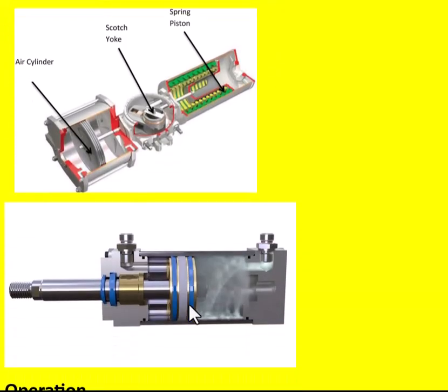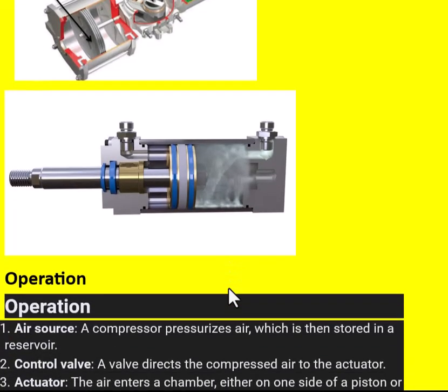And this is how the original instrument looks. This is the piston, this is the piston rod, and this is one compressed air chamber connection or control valve. This is another compressed air room, which has the control valve. The purpose of these control valves is to send the high pressure air into their respective chambers to get the work performance from this actuator.